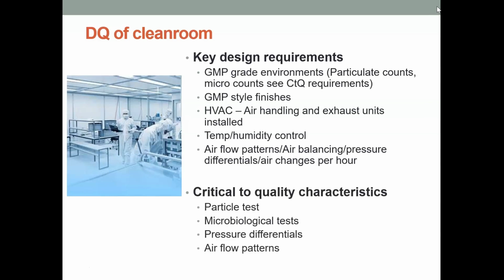The critical to quality characteristics for this would be your particulate test, your microbial tests, your pressure differentials, because that's keeping your room clean, and where your air is flowing, your airflow patterns. So these are all critical things that would have to be managed as part of the qualifications.